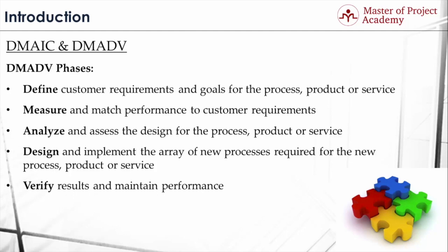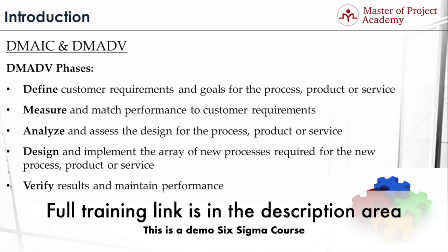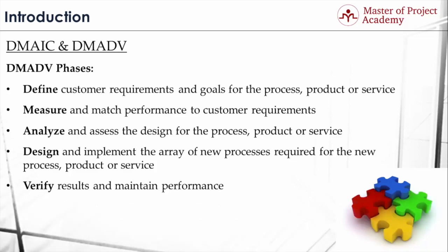The basic difference of DMAIC and DMADV frameworks is DMAIC will be used when you are trying to improve or develop a process which is already in existence. However, the DMADV, define, measure, analyze, design, verify method, aims to redesign a problematic process or product. The approach initially follows the first three steps of DMAIC and then deviates in the last two steps by introducing design or redesign and verify or validate the steps to gain the improvements needed. This approach prevents problems from happening through quality and robust design concepts.